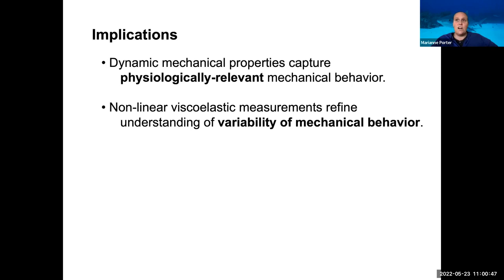And as we start to explore the quasi-static behavior, just varying the strain rate, how fast we're running our test, and how far we strain the material are all going to give us really great insights into overall how our sort of squishy biological materials are going to work.